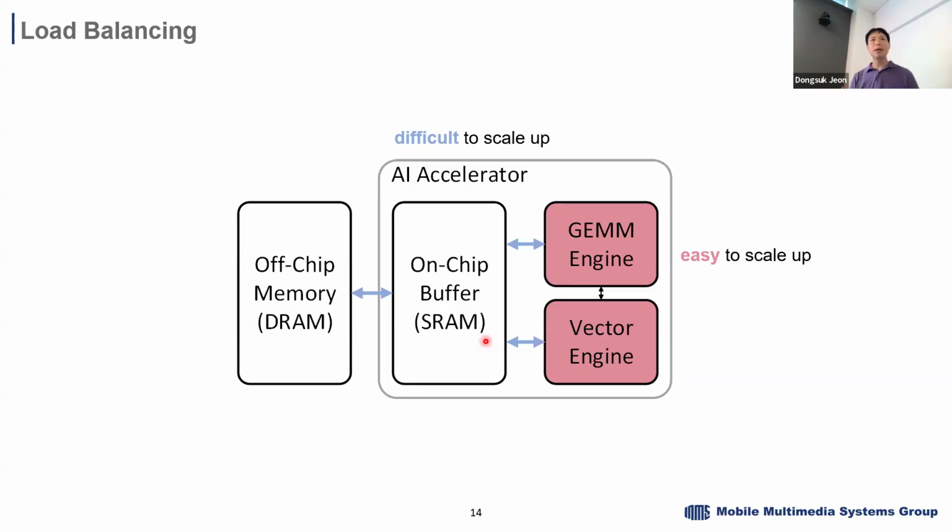The space of the memory is one problem, but the larger problem is the bandwidth. Even if we store everything in the external DRAM, the speed of this read and write data bus is very limited. It's usually much slower than the computing circuit itself.